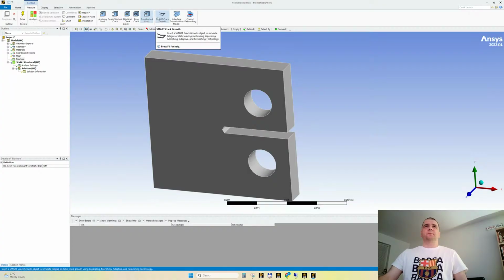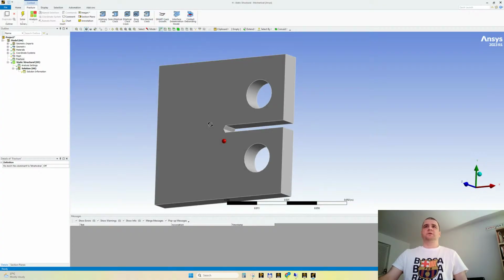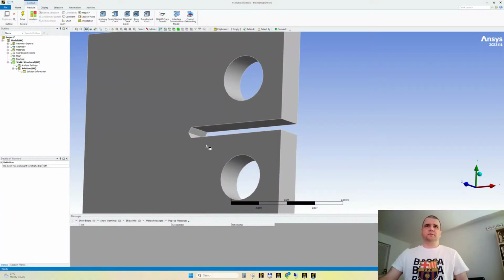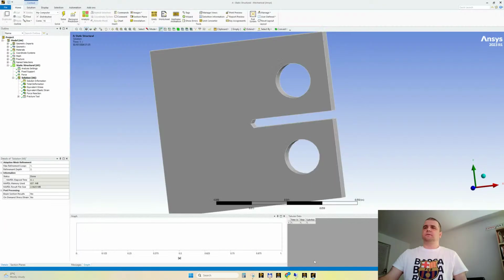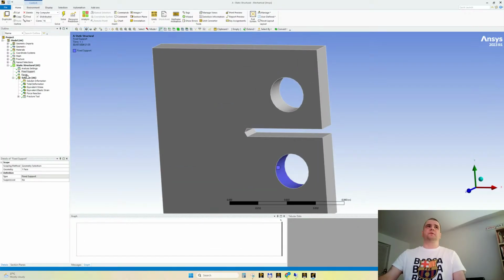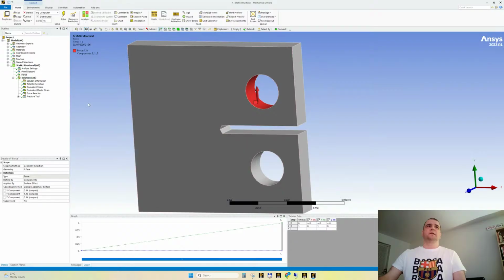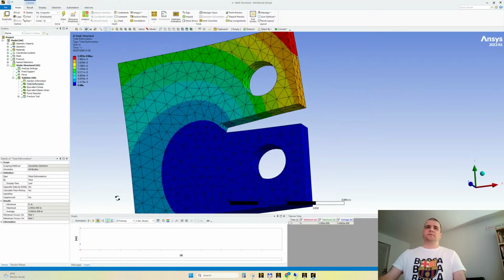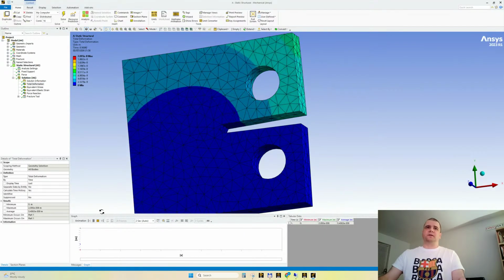So today we are using pre-meshed and smart crack growth. I will show you this geometry that is not correct until we notch it even further with a very small acute angle pre-crack, let's say, or a crack initiation. And I would like you to see that it didn't work, okay? It didn't crack. Yes. Look here. So I have fixed here, I have pulled outwards, and there is no cracking, okay? Let me animate. There is no cracking propagated here.